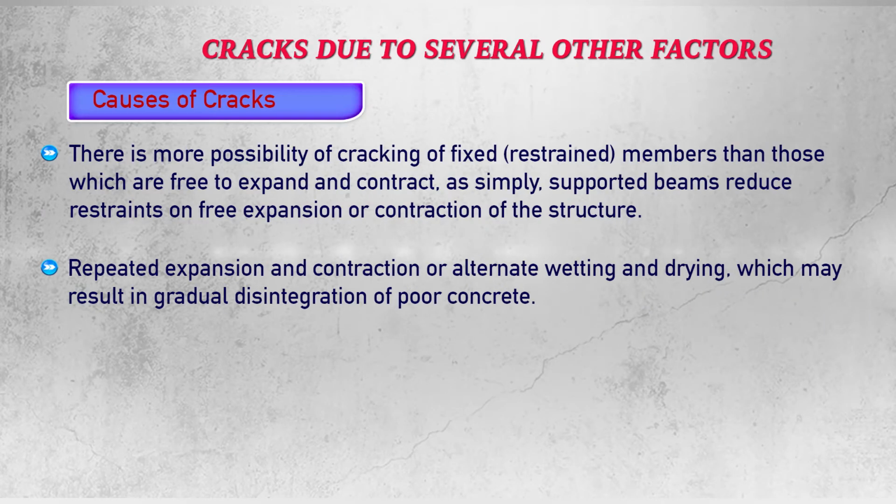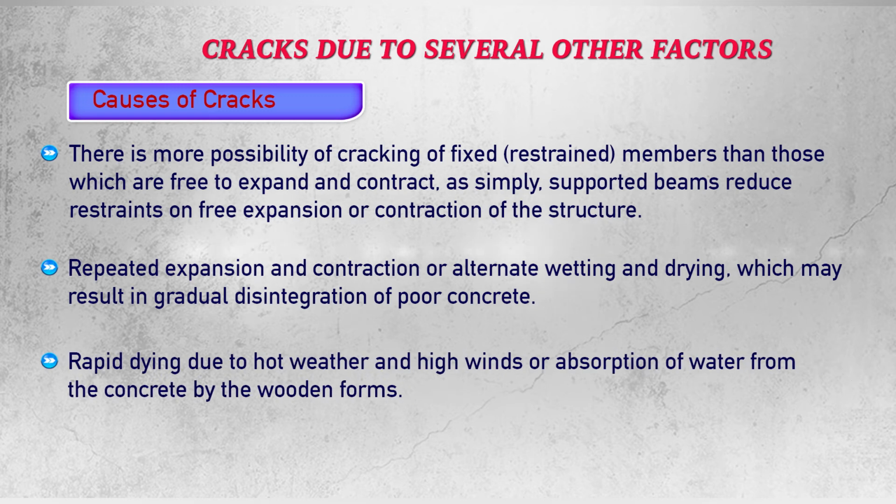Then repeated expansion and contraction or alternate wetting and drying, which may result in gradual disintegration of poor concrete. Rapid drying due to hot weather and high winds or absorption of water from the concrete by wooden forms. The formwork on which fresh concrete is placed must be damped, or it should otherwise be waterproof so that it does not absorb water from the concrete. Ensure adequate moist curing of the concrete.